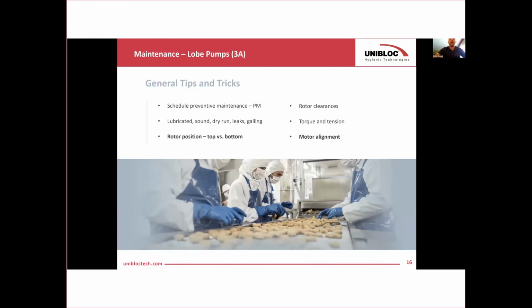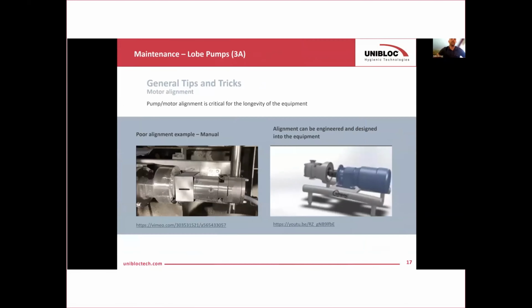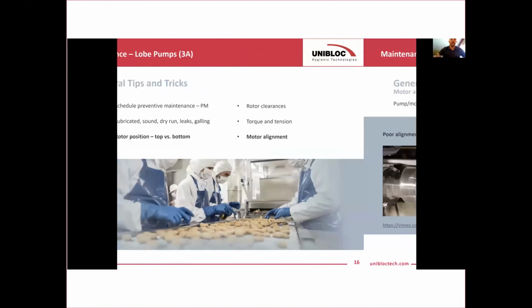Otherwise, you will end up having excessive vibration, which will then cause premature failure of the pumps and the bearings. So I'm going to show you an example here on a video where you can see a pump and a motor that has not been properly aligned. And I'm going to play that for you here.